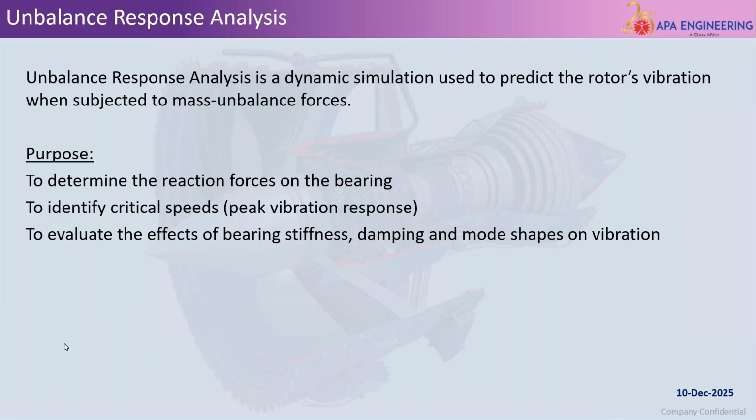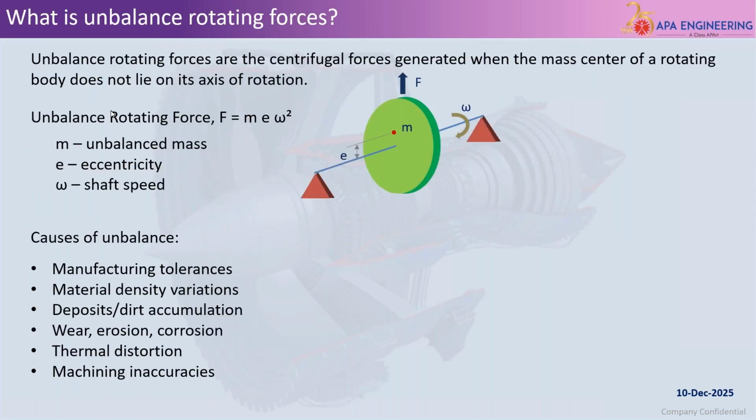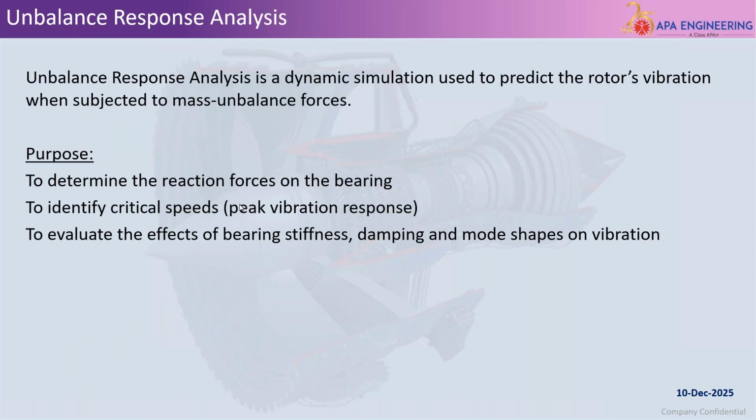So let's see what unbalance response analysis is. Unbalance response analysis is one of the most important simulations in rotordynamics. It predicts, like I said earlier, how a rotor will vibrate when it's subjected to a mass unbalance, like the unbalanced rotating force we saw in the previous slide. What if the unbalanced rotating force is acting on the rotating equipment?